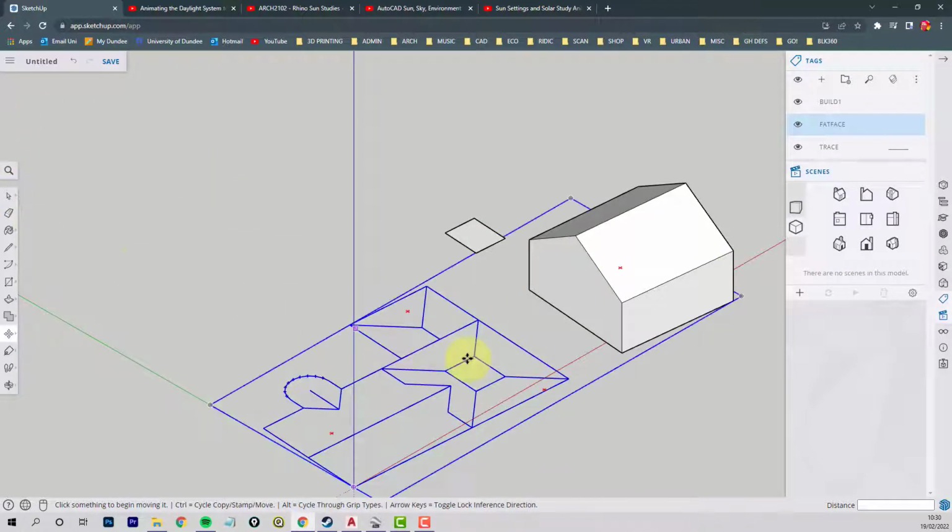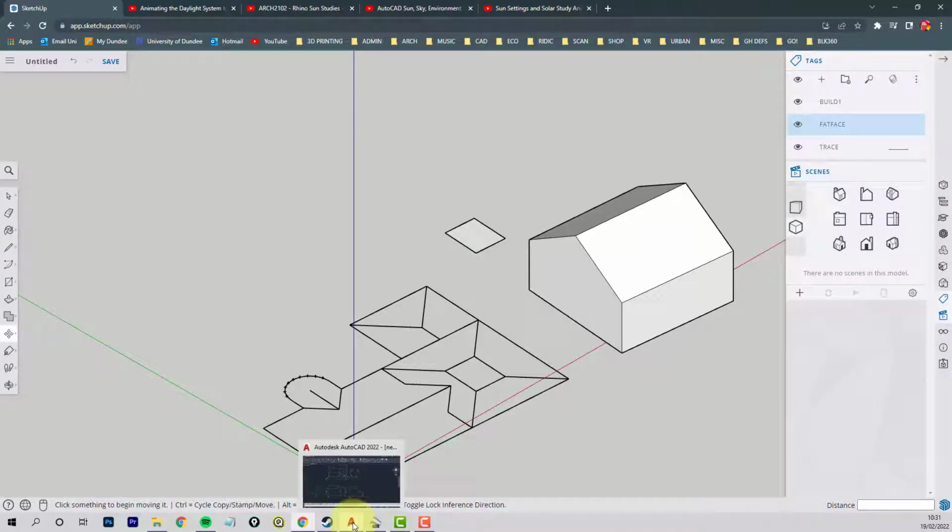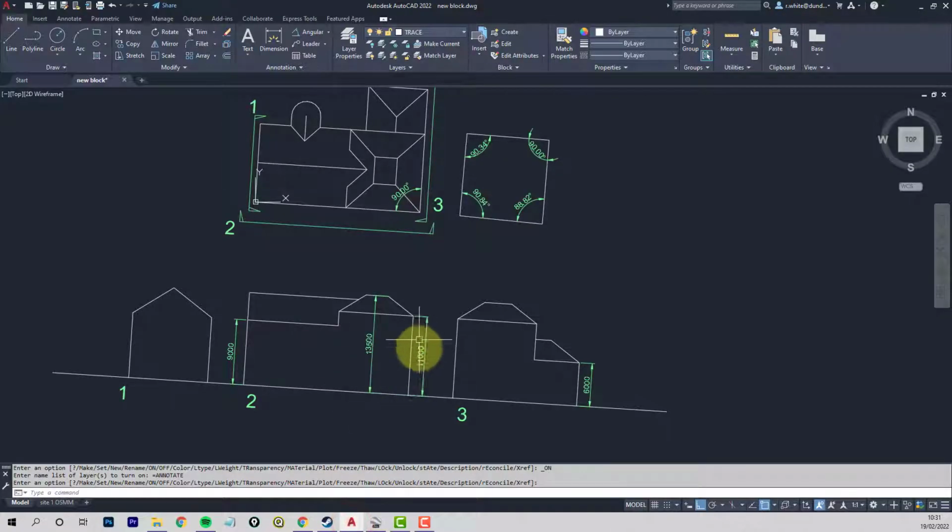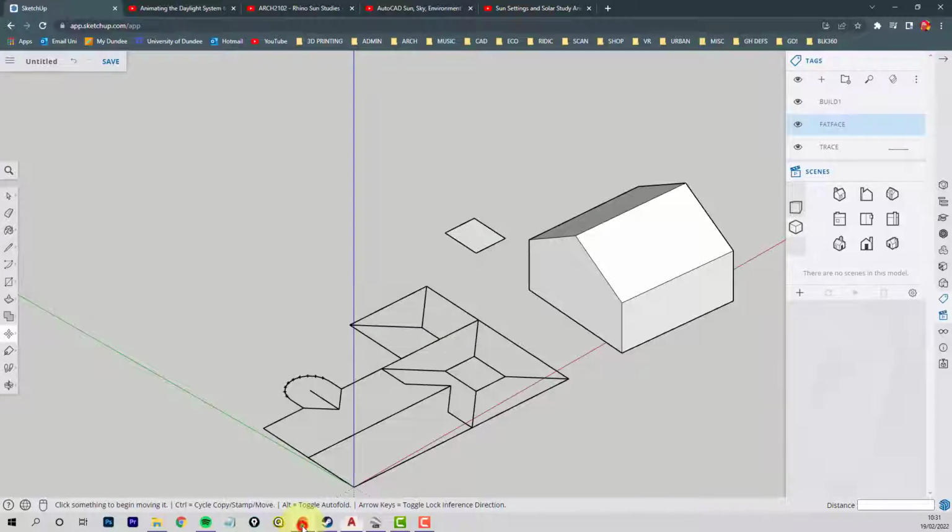Okay. So let's bring the walls up now, and then we can put the roof. The roof should just be a simple infill because everything's worked out already from CAD. So we're looking for a height of 11,000 for this part of the building. Okay, so I'll just trace around it. I don't want to snap onto the red axis or the other, so turn the inferencing off.